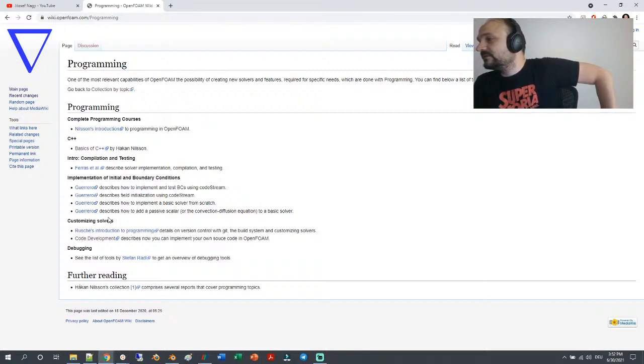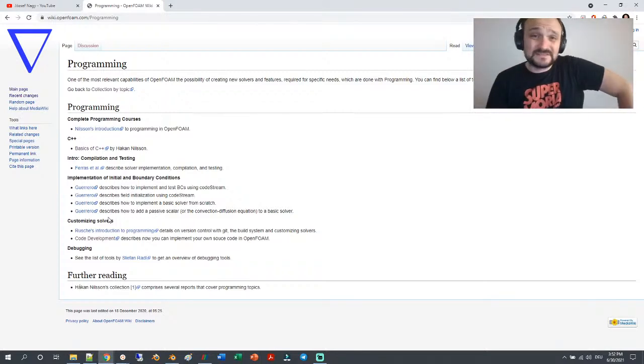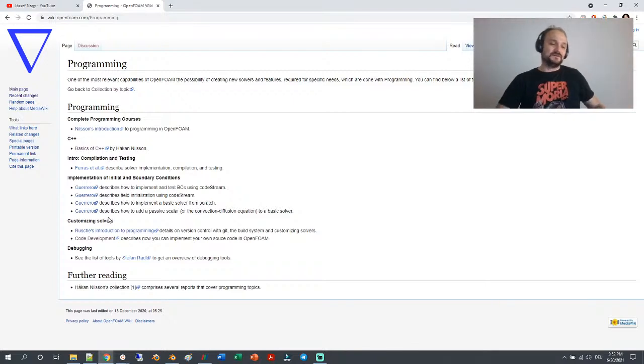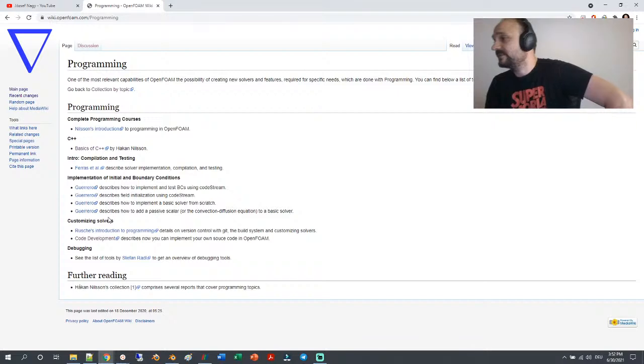In the case of a CAD model, not CAD directly, so not IGES or STEP files. You can only use STL and OBJ files, unfortunately. So you have to convert those into STL and then divide the STL into your patches, and then you can run snappyHexMesh.